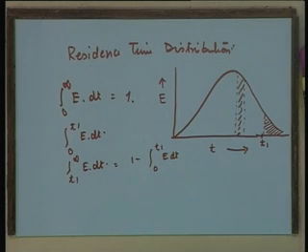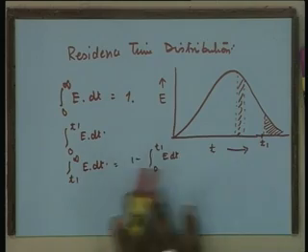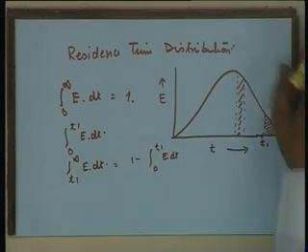One can essentially get a picture of this residence time distribution experimentally for a given reactor system, and it can give you an idea about the nature of non-ideality of a reactor system in terms of flow behavior. Mind it that non-ideality may also be caused by other reasons like mass transfer, partitioning, or a variety of other reasons that we have discussed, but this non-ideality we are talking about exclusively in terms of the flow behavior.